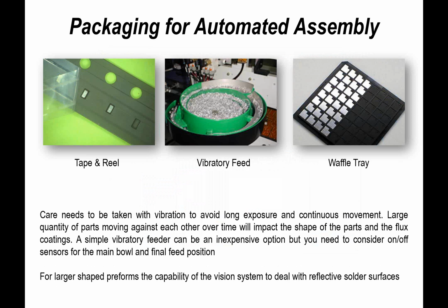A couple of things: vibratory feeders, they can change or affect the dimensions of the preforms. So be aware of that. And it's continual vibration. If you're getting moving parts and they're sitting in there for hours, it's important to make sure, if you are considering that route, to look at preforms and the feeder mechanisms and see how they sense the amount of parts that are in the feeder and the final feeder tube prior to pickup. But if they're just going around and round and round for hours, they will damage it. They will remove flux from the surface.